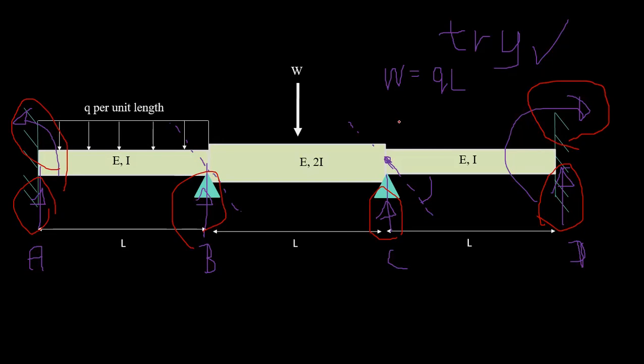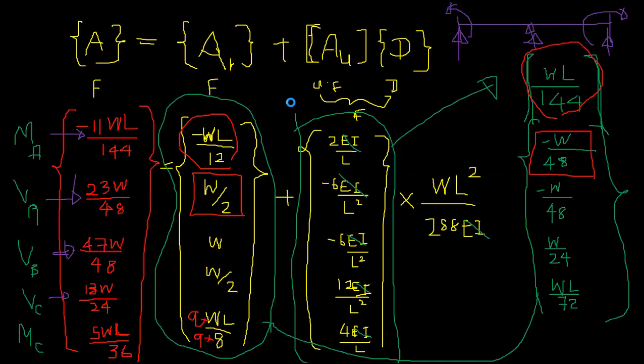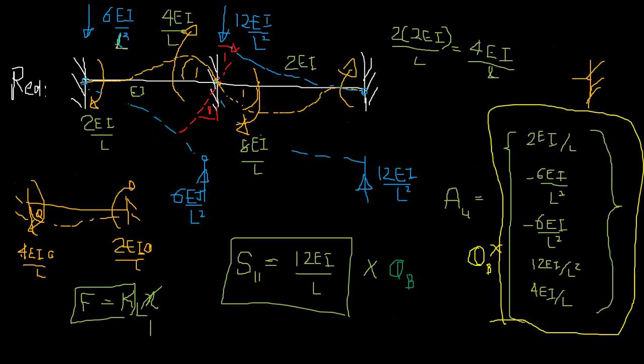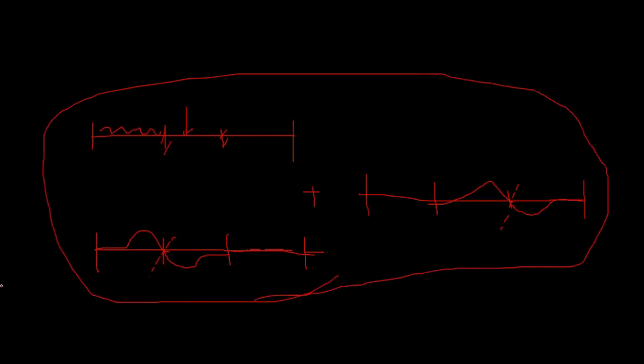So when you add displacement like this, you have to add each at a time, right? So this is your primary structure, you fix everything with loading, and then secondly you will be applying a unit displacement to this location, right? And third, you apply a unit displacement to this location. Okay, so once you add all of these three, you will get the final structure, right?